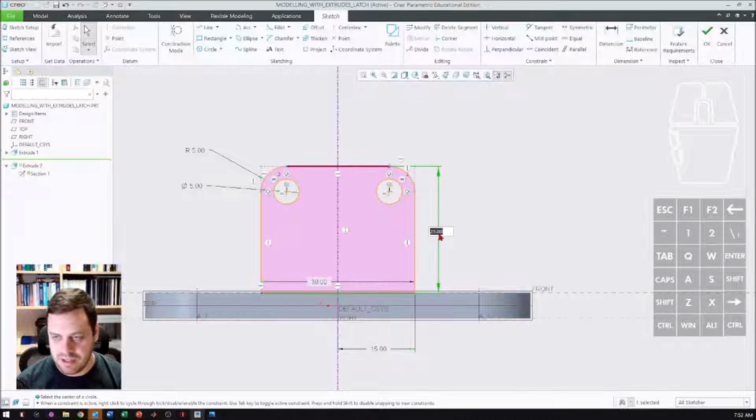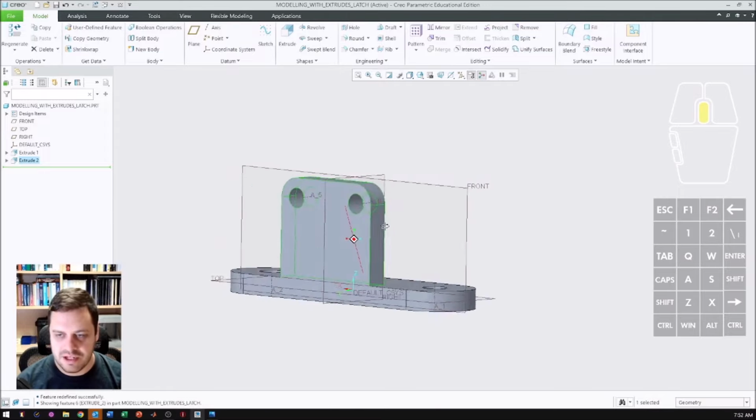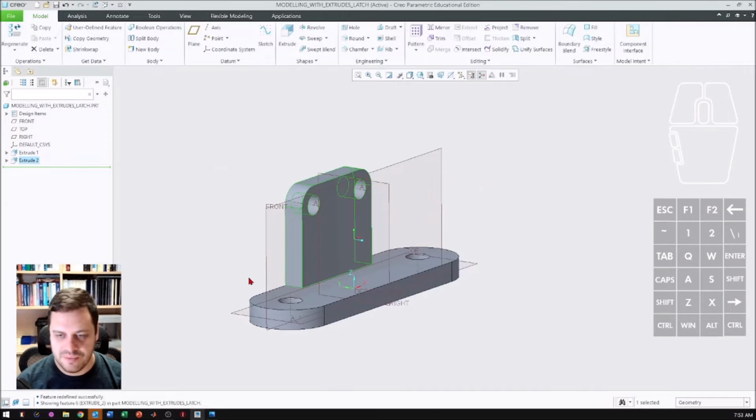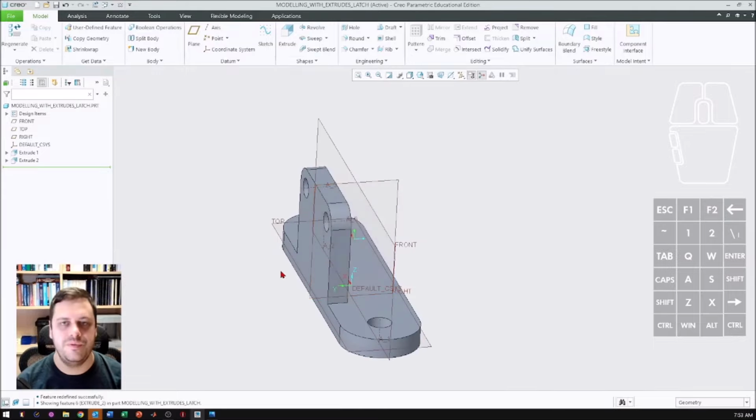So you may see if we double click this one and change that to 25, that has stayed as that reference dimension, and that's simply because it's picking up the reference of this dashed line, which is fine as well. As long as the dimensions are the same as what's on the drawing, you're good to go. So if we click through and go OK, you can see that's simply updated that object, and now our second extrude is just off that top surface and not eating into the side of this particular one down below as it was before.